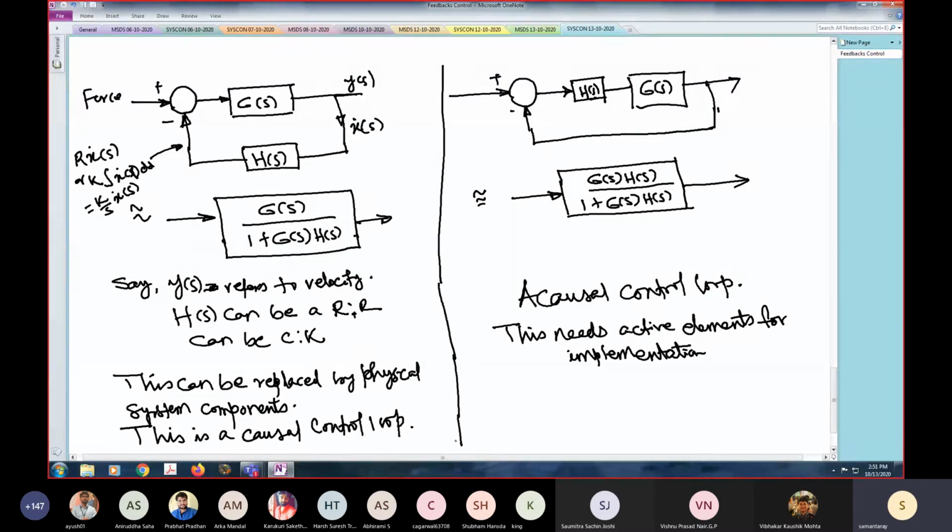So I do it outside the system. I take the measurement and pass it through the analog circuit. Maybe I have a real mechanical damper, or instead I represent that by an electrical resistance. Instead of a mechanical spring, I represent that by an electrical capacitance. And I ultimately produce the equivalent of a force, which I then apply on the plant.